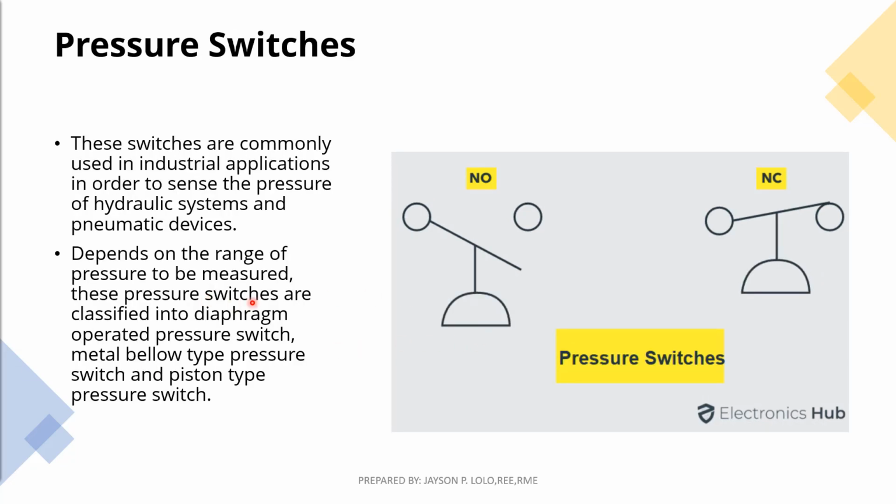Pressure switches. In all these types, pressure detection elements operate a set of contacts which can be either double pole or single pole contacts. This switch symbol consists of a half circle connected to a line, where the flat part indicates the diaphragm. These switches may be either normally open or normally closed type configurations.